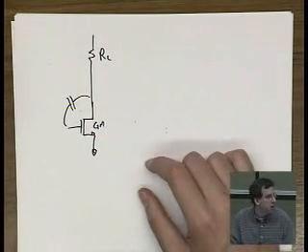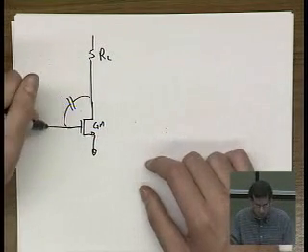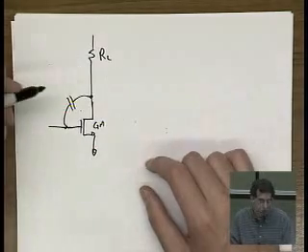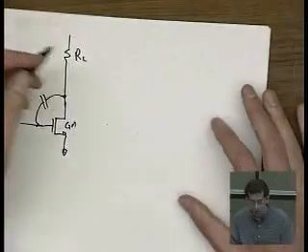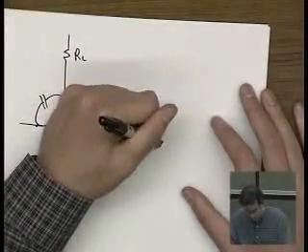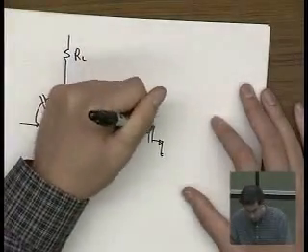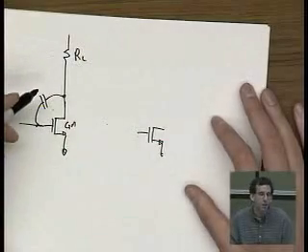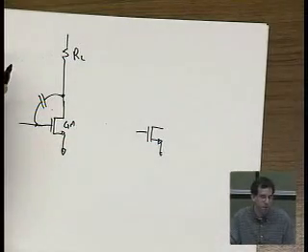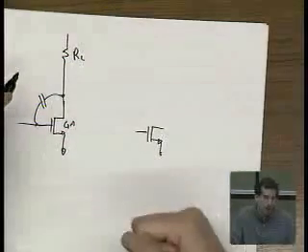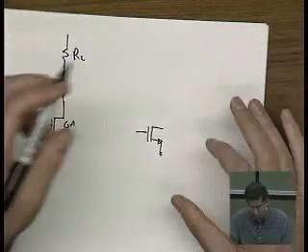And that really limits the bandwidth. Now, what can we do to avoid that? We can avoid that by using a cascode. The reason why this Miller effect happens is that this capacitor provides direct coupling between the input and output. So if you can break that coupling path, then you're in good shape.